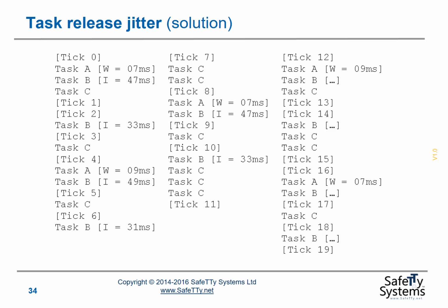So this slide shows the core of how we can make this calculation. So the key to understanding the release jitter in task B is to assume that task A has its worst case jitter behavior, which means that what we'll assume is that every time task A runs, it runs alternatively with its worst case, then its best case, then its worst case, then its best case execution times.